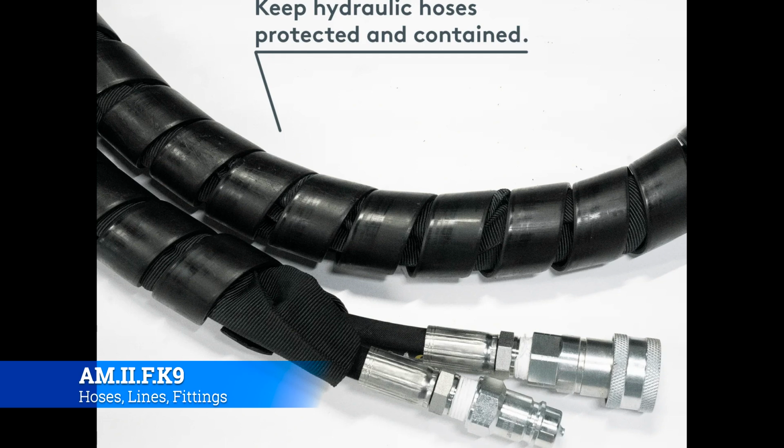Now with the other approaches, even with the Adel clamps, you can push the hose down and look into the clamp and see if it's starting to deteriorate. But with the snake skin, it covers up the entirety of the hose, so you'd have to take that entire thing off, and it's not necessarily the easiest stuff to get on or off. Especially whenever you take it off after it's sat for a while, you can stretch it out and make it where it doesn't want to go back on, so then you're having to replace it all the time. So as a general rule, I try to stay away from this stuff and only use it whenever there's not really any other option.